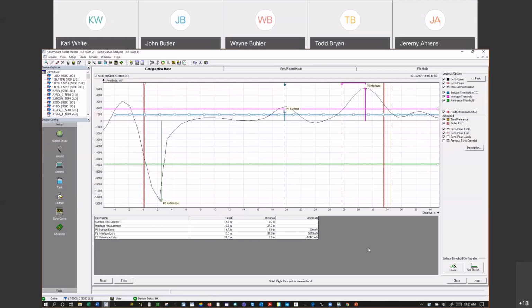Yeah, John, I've had a few cases where they've said that. They go, well, look at the magnetic level indicator. It says the level is 6 feet, and you're saying the level is 8 feet. And you take your infrared thermal gun and you shoot up and down the pipe that the MLI's in, and you can see the temperature change, and it's right where the radar says the level is, right? The float isn't floating where the level is, but right. Yeah, you can usually tell by temperature change right where that level is, and you go, yeah, your float's not floating. Yeah, radars don't lie.